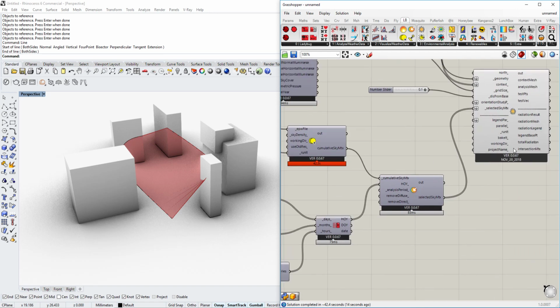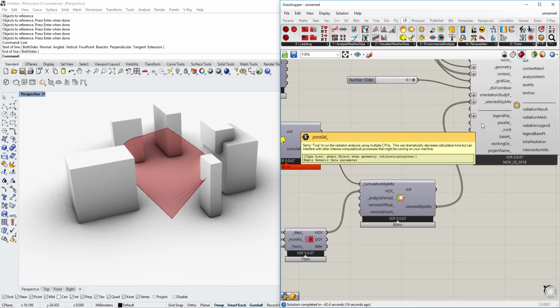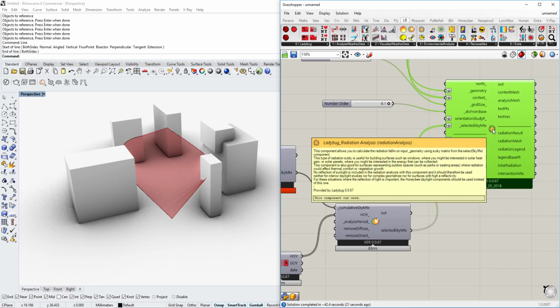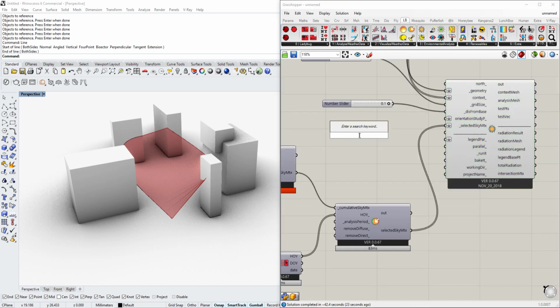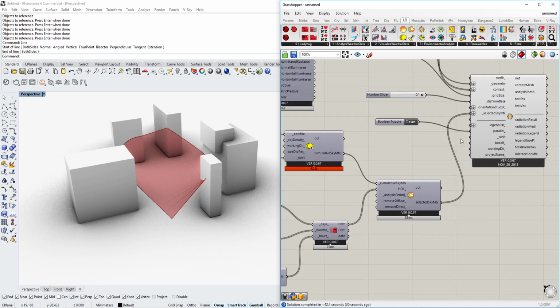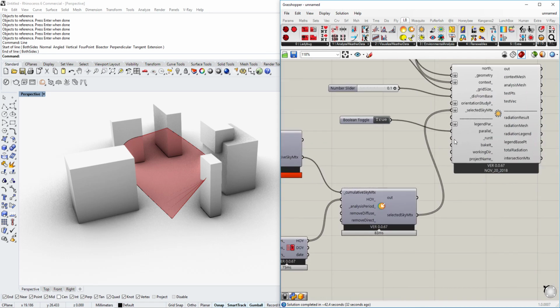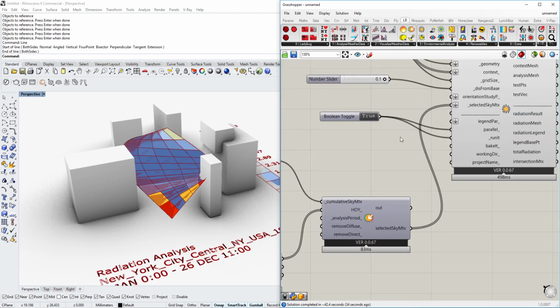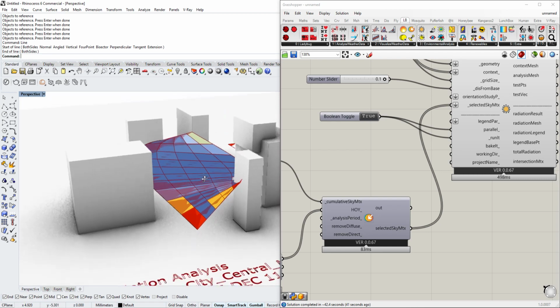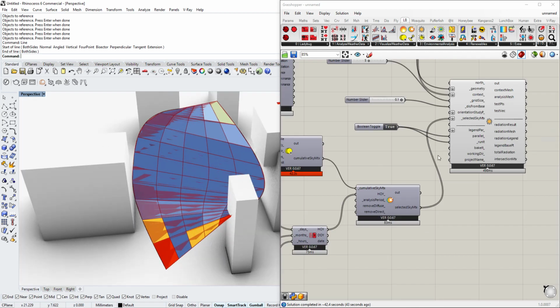So this took the time to do it, and as well for the radiation analysis, there's also a tool to use your multiple CPUs, which most computers have nowadays, parallel, so we set this true as well. And then we are also gonna run it. We just use the same one here. And again, we have to wait a little bit. Well, that was pretty fast, I guess. And it gives us the radiation analysis of our thing.